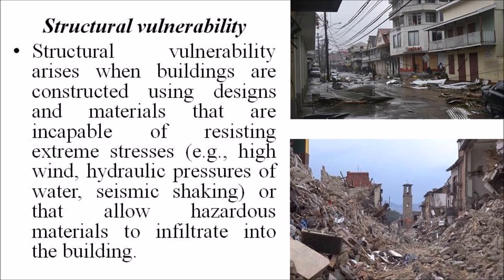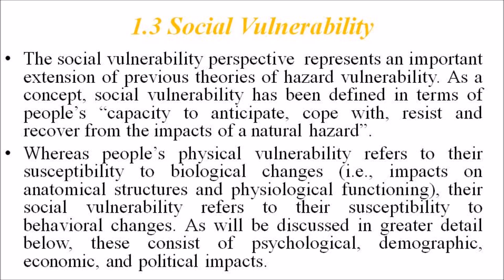The construction of most buildings is governed by building codes intended to protect the life safety of the building occupants from structural collapse, primarily from the dead load of the building materials themselves and the live load of the occupants and furnishings, but they do not necessarily provide protection from extreme wind, seismic, or hydraulic loads, nor do they provide an impermeable barrier against the infiltration of toxic air pollutants.